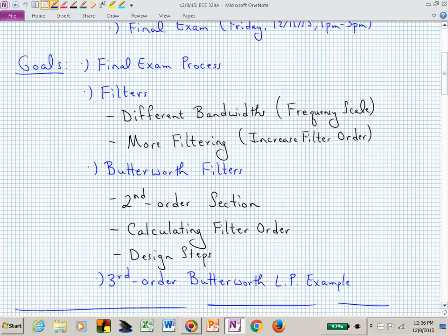Well, I just put two of these second order sections together. I cascade them. If I need a fifth order, I have the two and I add a fifth. The coefficients will obviously be changed, and we'll have a table for determining where those Butterworth coefficients need to be in order for those circuits to produce the transfer function that you want.